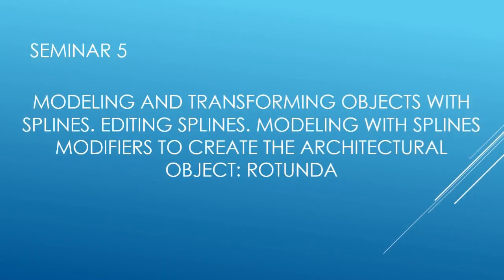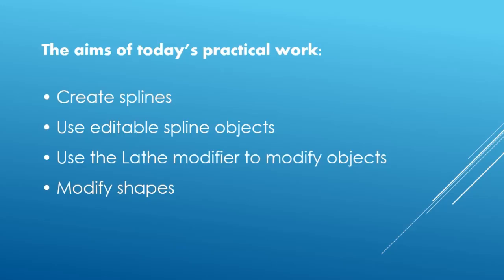The title of today's lesson is Modeling and Transforming Objects with Splines, Editing Splines, Modeling with spline modifiers to create the architectural object rotunda. The aims of today's practical work: create splines, use editable spline objects, use the lathe modifier to modify objects, and modify shapes.